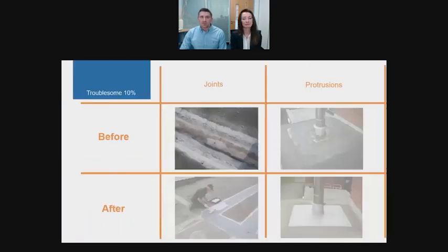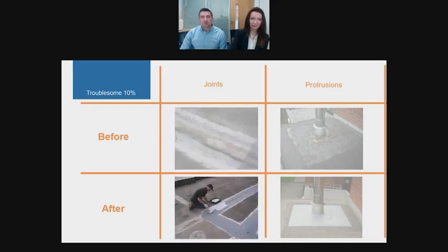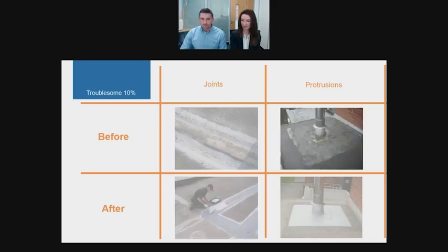So if we look at joints and seams, all the movement of a building is concentrated at the weak points. These can occur either between two separate parts of the building or two dissimilar building materials. Therefore, when a leakage occurs, its origin can be generally traced back to its weak points. So a flexible solution would be ideal in this repair. In this picture, they purposely chose a membrane like this because it could be used for just the joints and they didn't have to coat the whole roof.